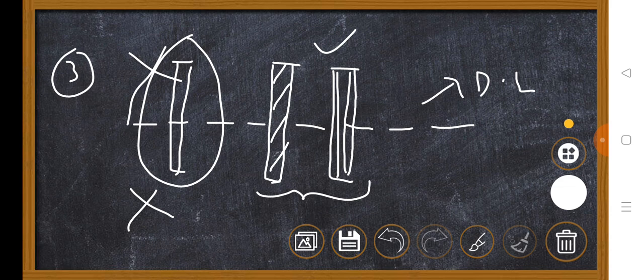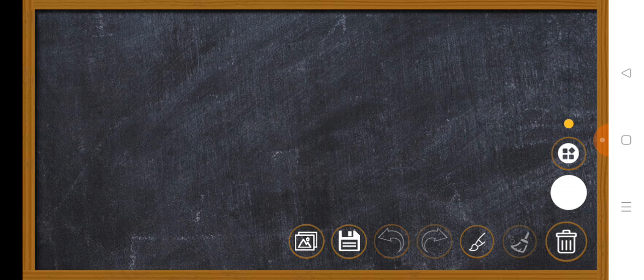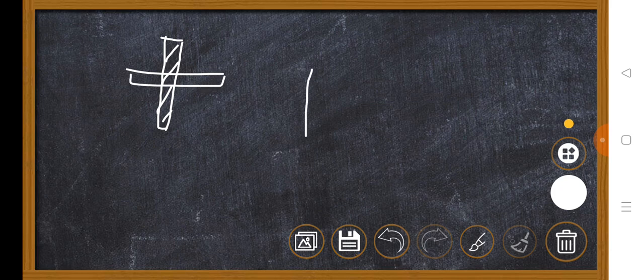These are the three different rules compared to NMOS and PMOS. And these are the similar rules compared to NMOS and PMOS. When polysilicon crosses diffusion, or when diffusion crosses polysilicon, a transistor is formed.